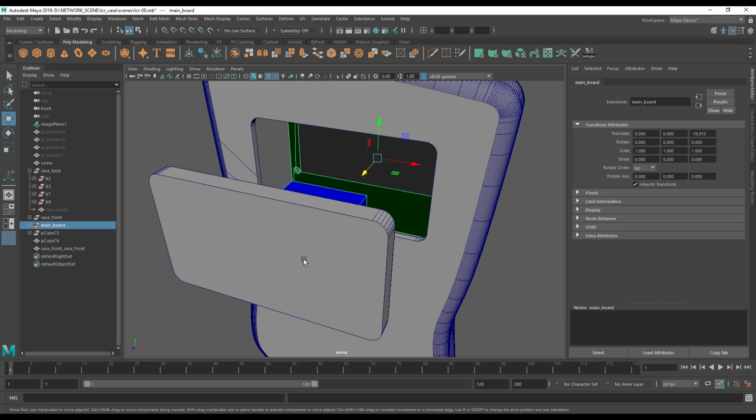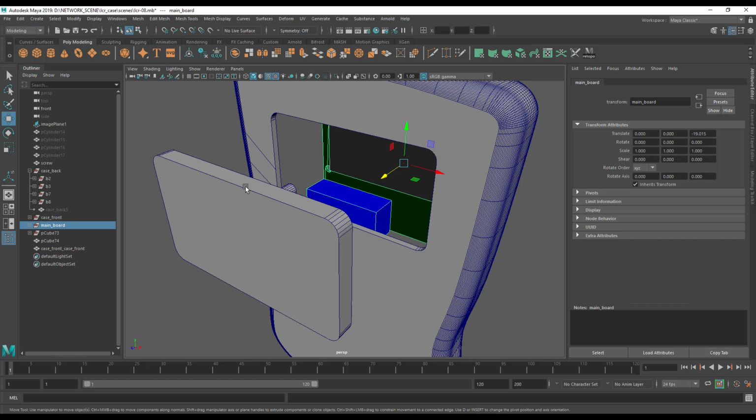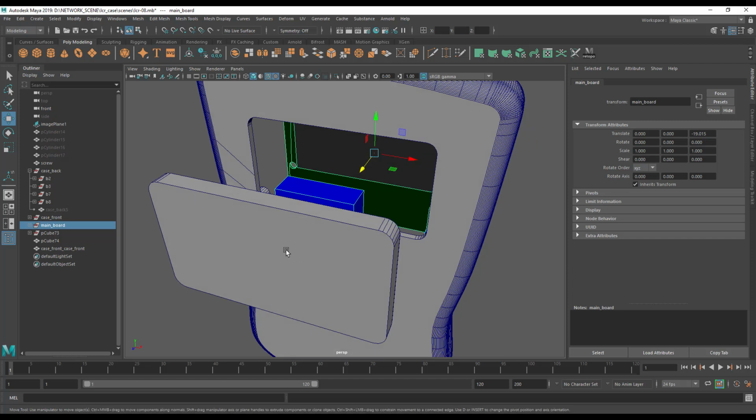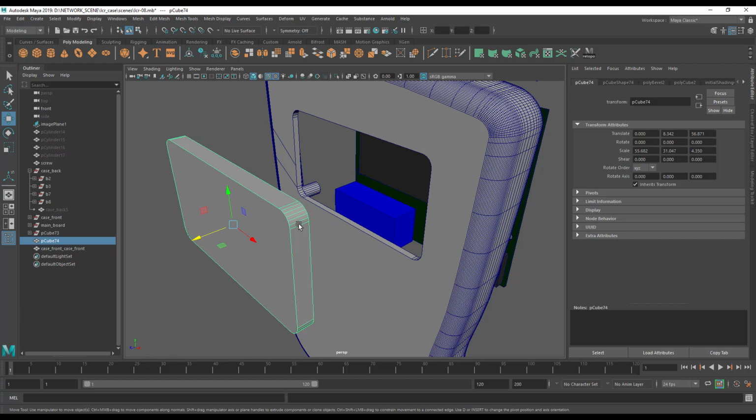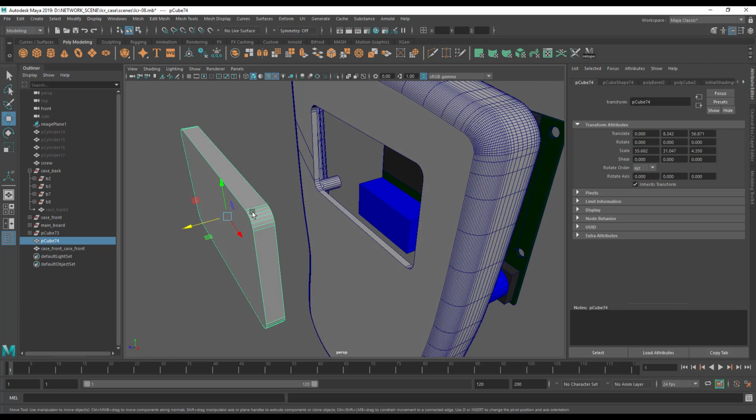So in order to achieve what we need, we'll need to have something this size but thicker, with a hole in the middle. So this is fairly simple. Now the other thing is that I need this to be 1mm thick. So if I come in and scale it down, I can just use this to scale it to 1mm.